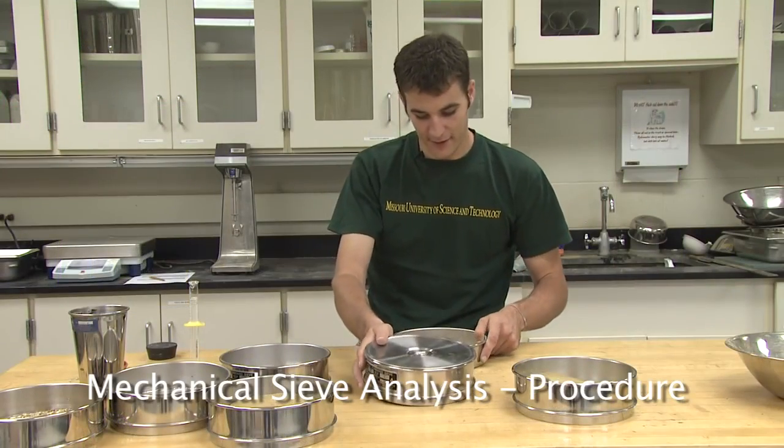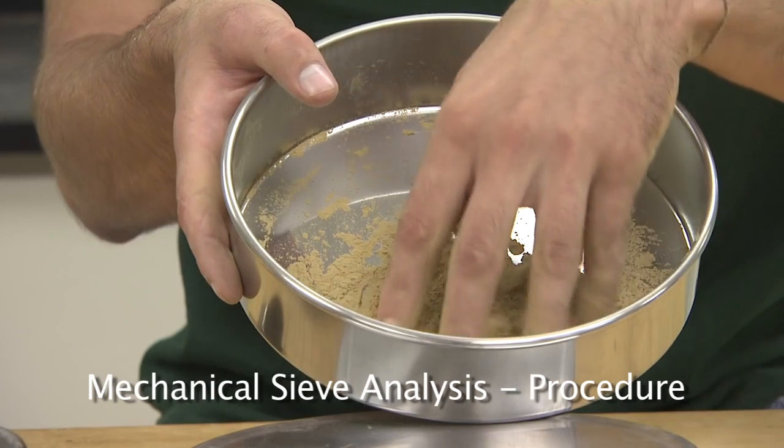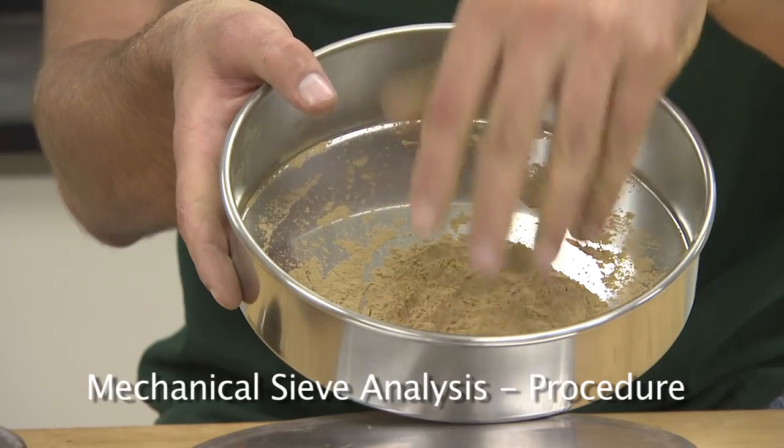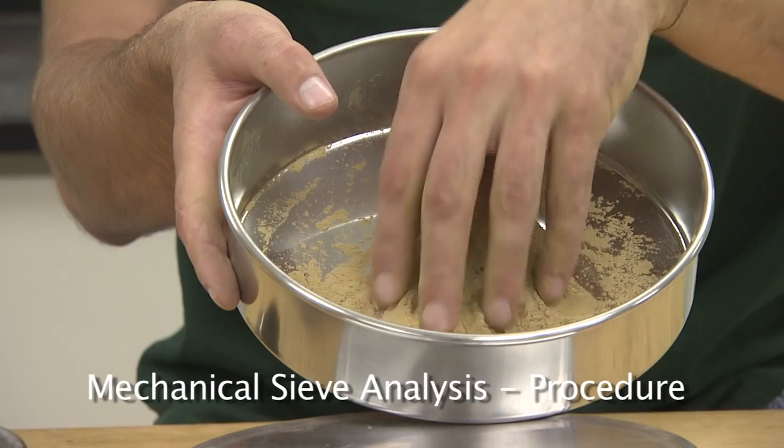Empty the material in the pan into a bowl and record the weight. This material is the material that has passed the number 200 sieve. It is considered the fine-grained portion of this material. This material will be used in the hydrometer analysis portion of this lab.